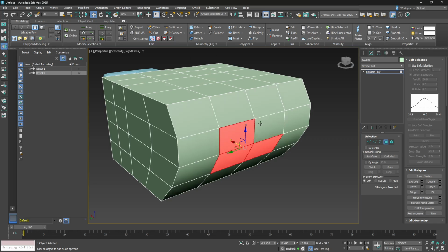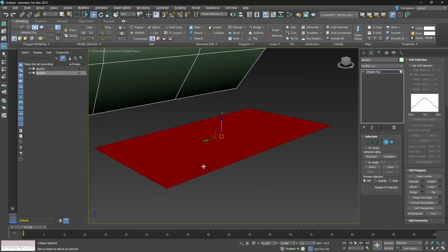This is a proper relax, unlike a lot of the add-ons for Blender, which just kind of don't do the right thing. Blender's alternative really is going into sculpt mode using the slide relax tool and holding shift. That's the relax tool in Blender. That works best anyways. And we can also create new faces in our case, right? So we can just click create, boom, there we got a new face now. Okay, kind of fun.